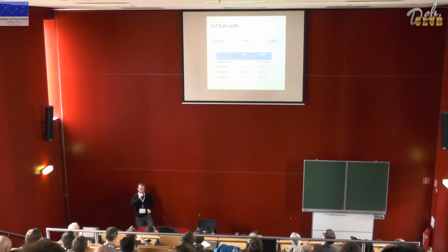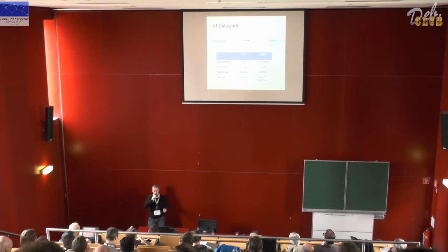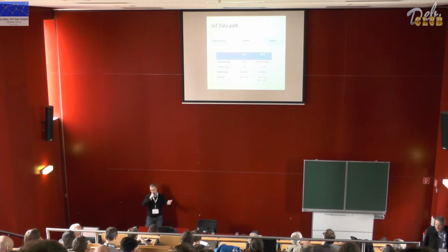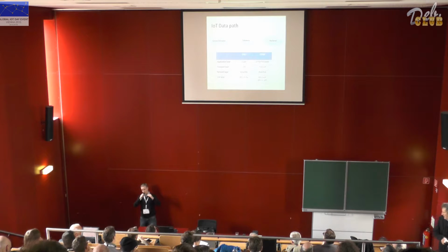That's because 6LoWPAN is transmitting the data from the sensor to the actuator via 6TiSCH multiplex. That's the time multiplex. We are dividing the communication channel into a table. We have several communication channels, and we are then dividing them into time slots.